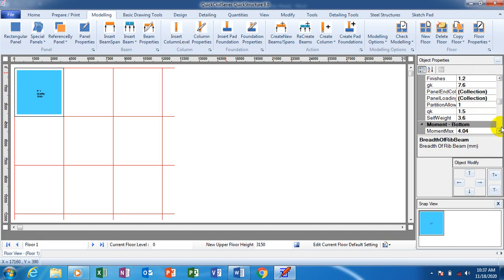And mind you, we have different classes of building. Since I'm just going to be doing this, I'm going to assume this is a residential building, so all of these values are very much okay, because your live load sometimes varies. This 1.5 varies. You can even have a live load as high as 9, even up to 12.